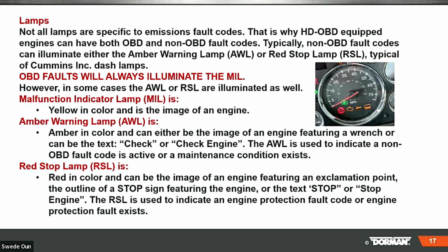So now the OBD faults will always illuminate the MIL. However, in some cases, the amber warning light or the red stop lamp are also illuminated as well.